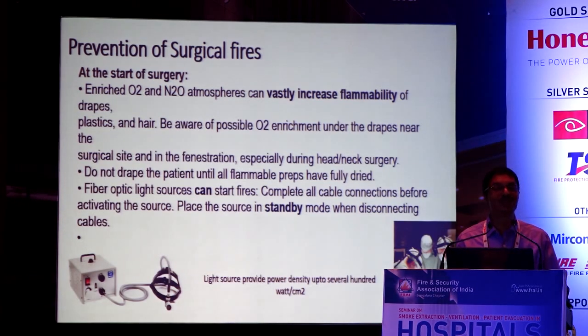Fiber optic light source. Earlier I was also wondering how the fiber optic light source can contribute, because some of the things we have not tested because we cannot afford to test it. But luckily some of the institutes like ECRI do send videos on what has happened, and they have simulation conditions. So a fiber optic light source can start a fire. It has a 300 watt xenon light source with a fiber optic cable of 1 meter. If the machine is not in standby mode and you take the cable out in an oxygen enriched environment, it may lead to a fire.